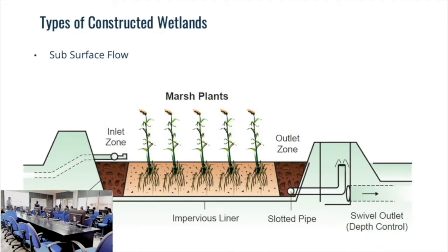And when we discuss the types of wetlands, there are different types of constructed wetlands. Based on our need, we can design the system according to our requirement. This is the mostly used system, subsurface flow, where the water flows inside the soil layer, so that we cannot see an open water surface on this system. Water comes in, goes under the soil layer and goes out. This system is mostly practiced in industry. We have applied the same kind of system to our coastal premises as well.